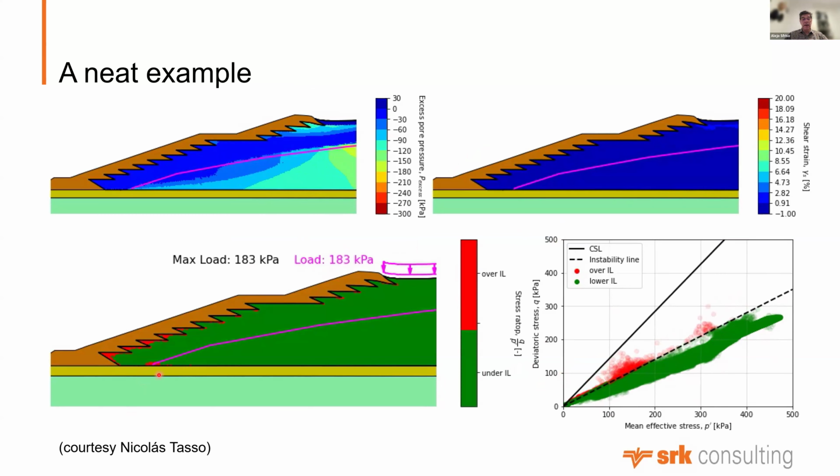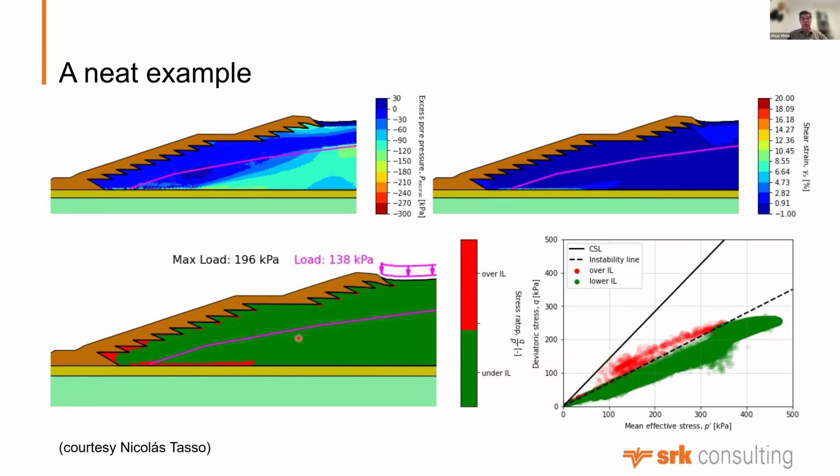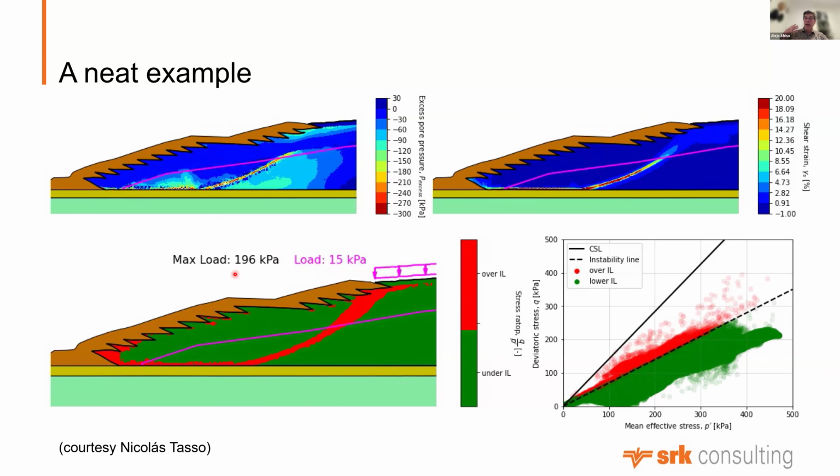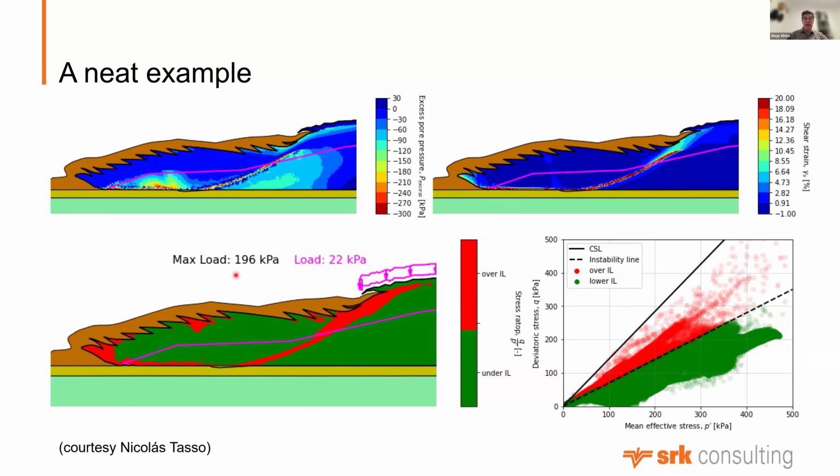And you can see here in red that a few of these points start to build up, and you see here it's growing. And at some point, this load is lower than this one, because once you reach this load, the progressive failure is initiated, and the thing will go away, whether you remove the load or not. So it's no longer up to you to remove the load. So you found a limit state here. This is one of the several points that were on that triangle.